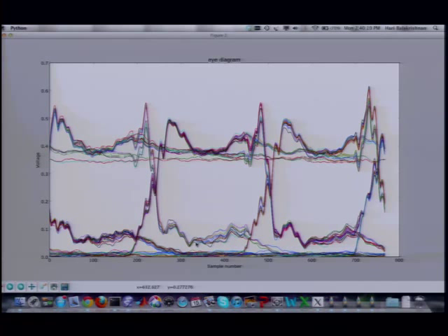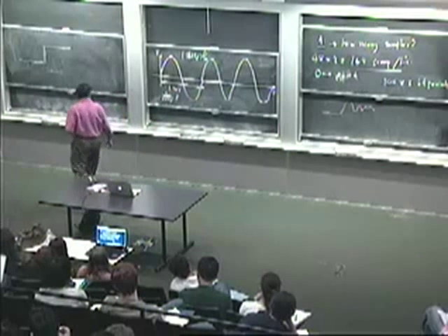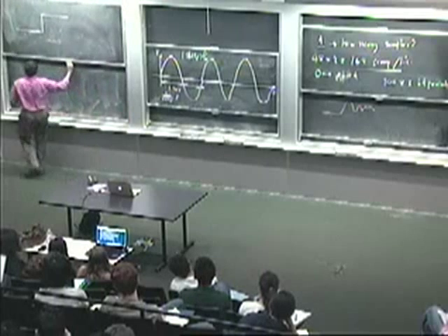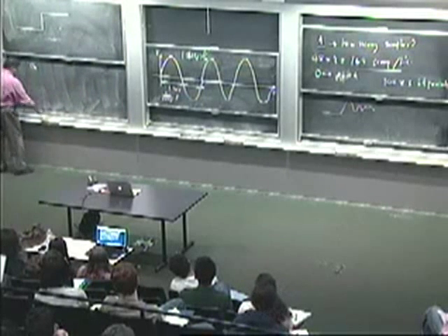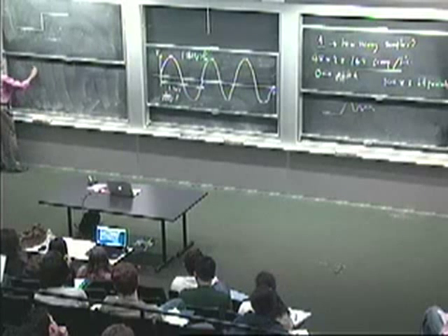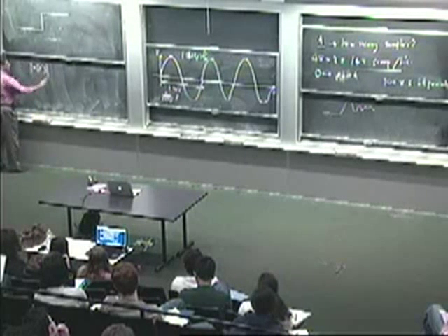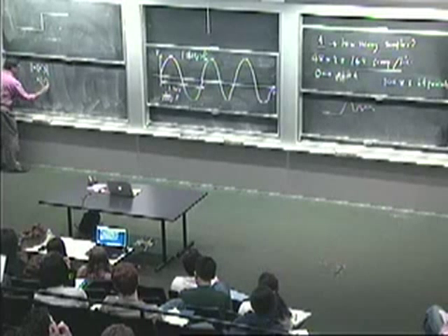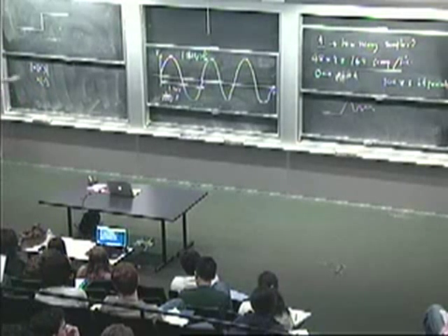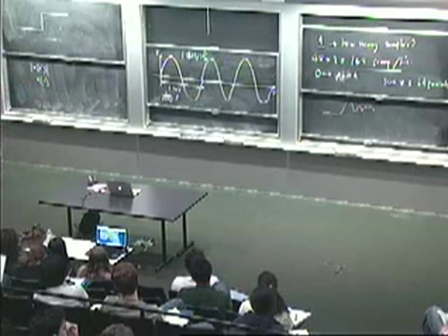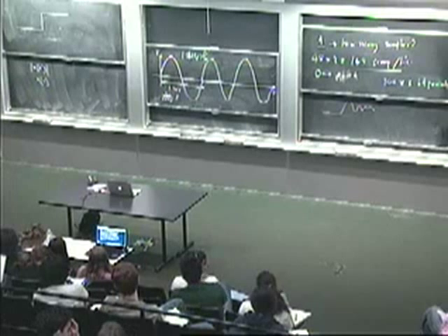And the reason is that the particular simple demodulation that we're using here for this on-off scheme actually makes that not look very linear for channels that have this kind of an overshoot to them. But the other scheme that Hari mentioned, the quadrature demodulation, will actually do a lot better. We in fact saw that. We saw that there was modulation that essentially pulled out the absolute value of what you were sending. And then there was another modulation scheme that actually pulled out the signal itself. And so if you're doing things like taking absolute value somewhere in the middle there, then you're going to start losing the ability to model it as linear.